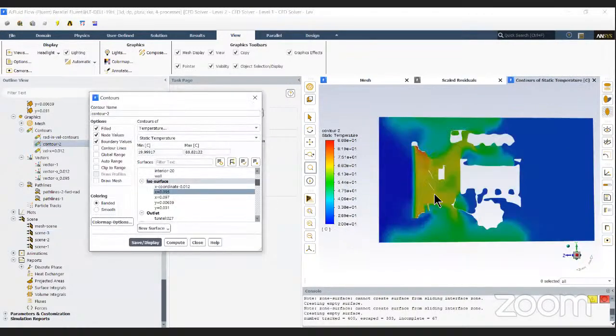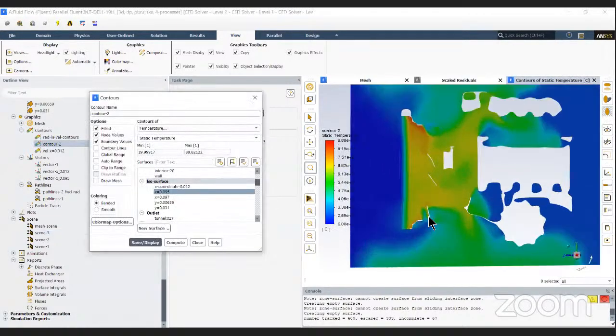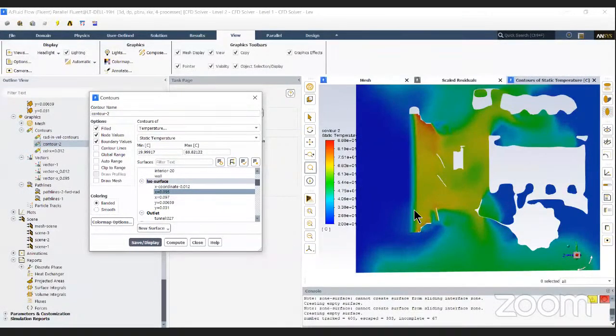if you are looking at the temperature in the cut plane, you will be able to see that there's cold air that comes into the radiator, and as the air passes through the radiator and comes in contact with the coolant, or rather exchanges heat with the coolant, your air gets heated, and this is the air that then goes into your engine bay.